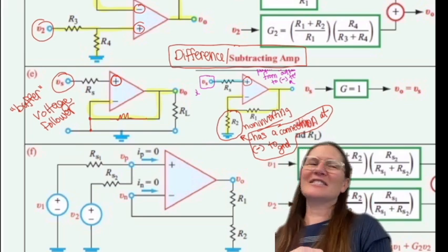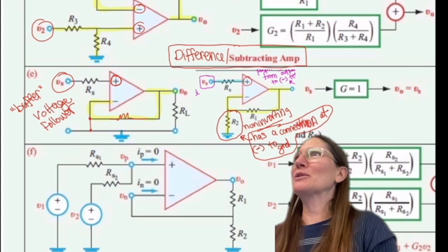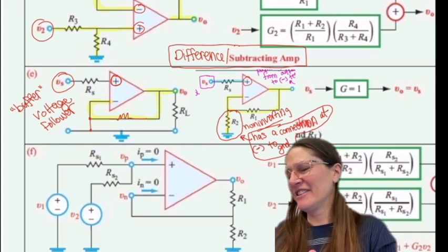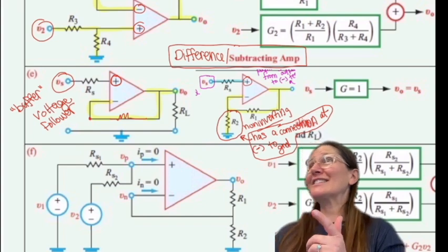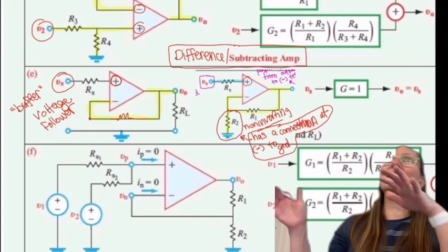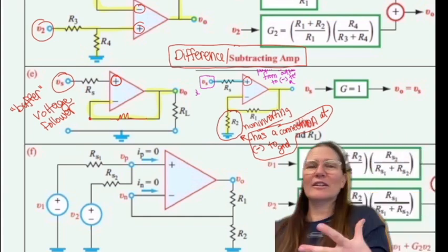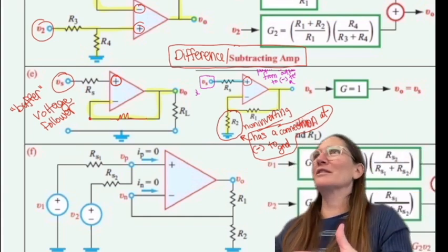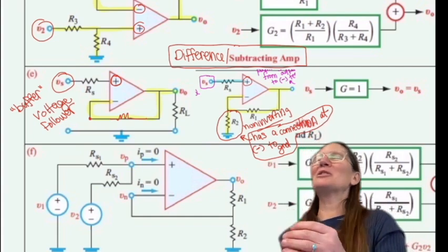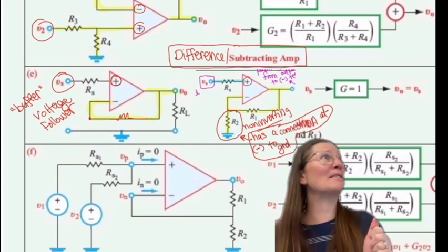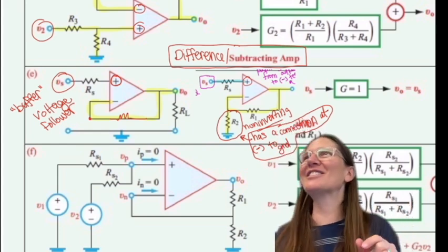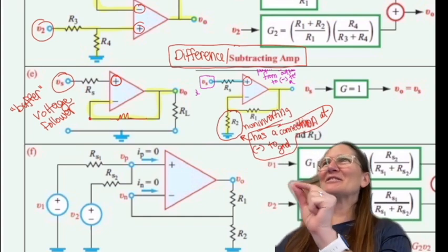It's going to not be happy with you. Okay, other questions though? But a good thought, yes, that would be kind of the concept, like yes, there's a pathway, so then is it the non-inverting, but it won't work like a non-inverting. So it will not be happy with you if you did that and may even blow your op amp, so don't connect it without a resistor there.